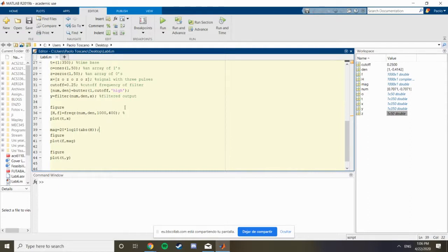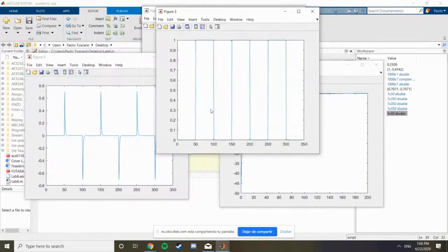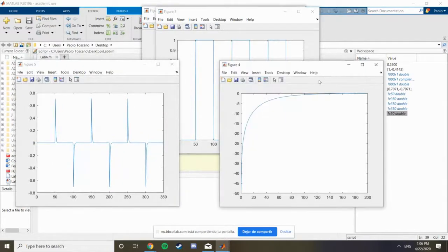Well, I think that's it for this part. You're supposed to get just these three: unfiltered and filtered. Then explain what you expect to see. At the edges of the pulse you have mostly high frequencies, and in the other parts low frequencies. You can also see that the high frequencies in the time domain signal are preserved, and the low frequencies have been removed.